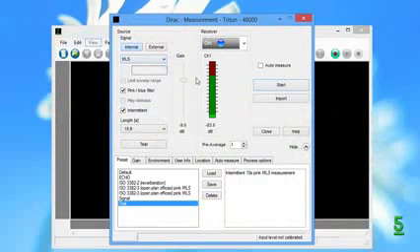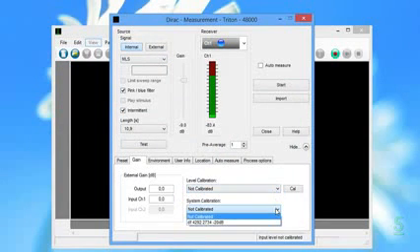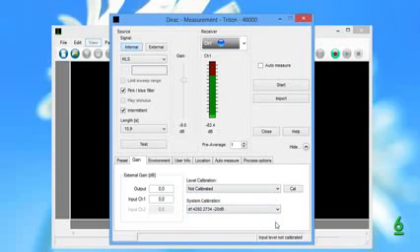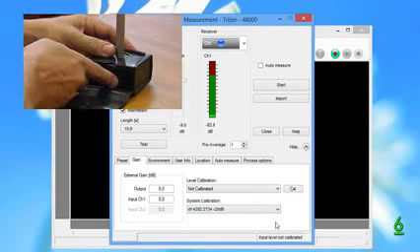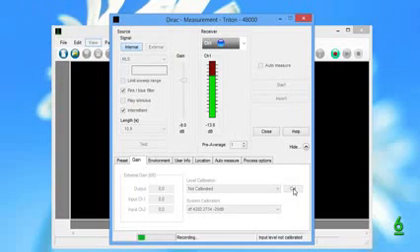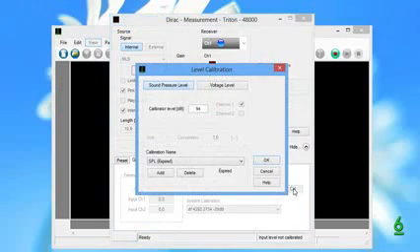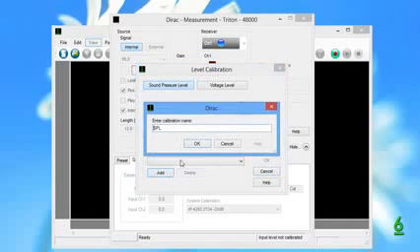Under the Gain tab, you can enter the gain settings for the external amplifiers, and this is where you select the active level and system calibrations. Here, you can start a level calibration. Insert the microphone in the calibrator and click the button labelled Cal. In the level calibration dialog, you enter the calibrator level and enter a name for the calibration, or use the default name.